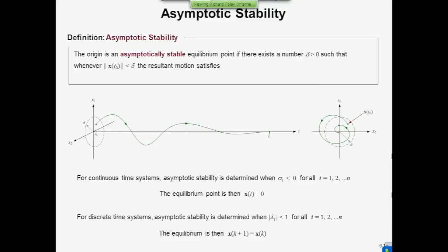Now, while we're on this slide, can I just make something that looks obvious very clear to you, so it's doubly obvious because it matters later. In the steady state for an asymptotically stable system, if it's continuous time, you know that the steady state is defined by x dot of t equals 0. It means that the state isn't changing anymore. It's reached its equilibrium point, and that is the steady state.